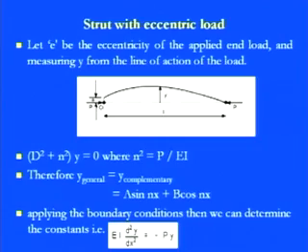So you see here in this lecture, as I told you, we are continuing with that strut part with eccentric loading. Because as I told you, in the Euler theory we are assuming that there is no eccentricity. But in a realistic way, we'll find that there is always some kind of eccentricity, because when we apply either the compressive or any kind of load, it is not exactly along the streamline, or we can say the centroid of the particular